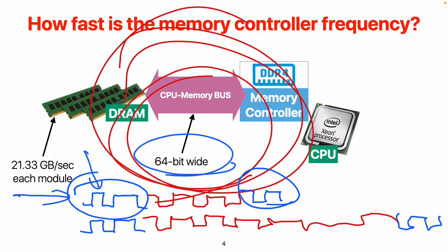So here's the thing: for this particular program, we make it go to DRAM if you call a synchronization at the end. In the given code, I think we are writing to the cache instead of directly writing to DRAM. So if I write 64 bits by 64 bits, we are writing to the cache, and the changes will not directly reflect in the DRAM.